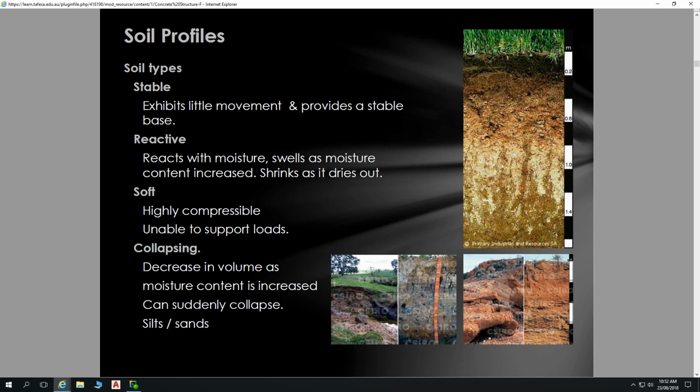But certainly we don't want buildings sitting on a tilt. That's not a perfect case scenario by any means. And then we go damaging pipes and cracking pipes and exacerbating problems because we get more moisture under buildings and so on. That actually happened in Victoria. I think there's a big court case going through where a lot of these houses were built on the waffle pod system, and the houses are all falling over or tilting over at different angles.